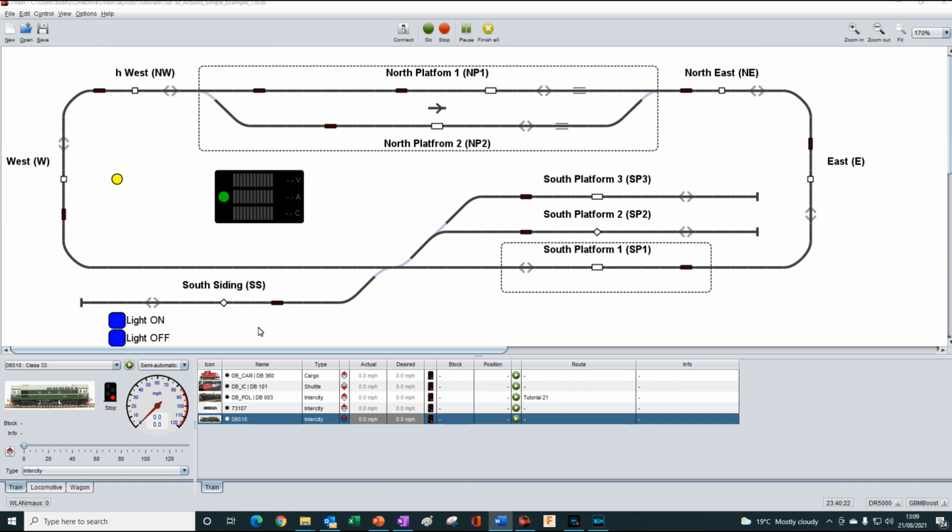And that is action buttons, a useful addition to the switchboard to provide a visual indication of the state of an action, to activate and deactivate an action, to interrupt an action, or to manually start the execution part of an action. But remember, manually starting an action completely ignores all of the conditions. So don't be surprised when the action executes, even when you know that the conditions have not been met.